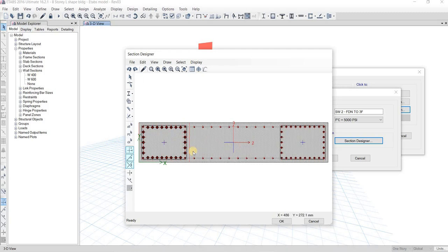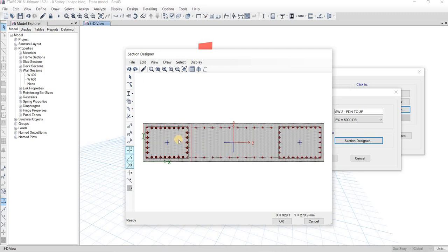Okay, so but in this presentation, this is the total number of rebar. But you can bundle it to have an adequate spacing for the actual construction. Okay, then we have a requirement of spacing from the NSCP that is equivalent to, I think, 2.5 times diameter or 50 mm.